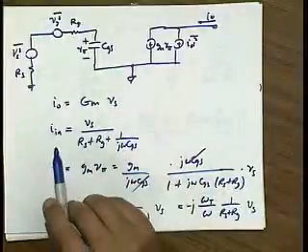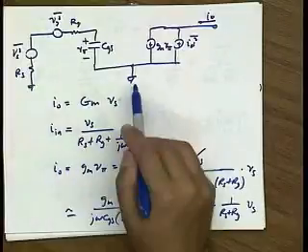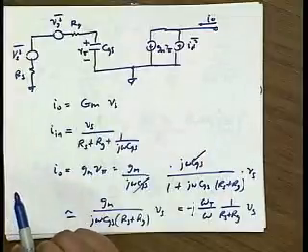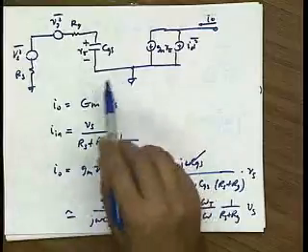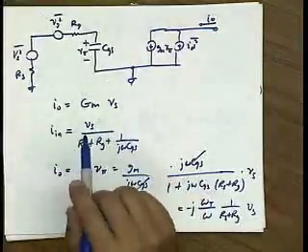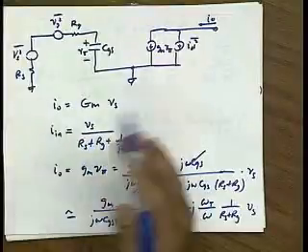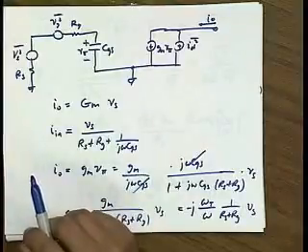Anything else that we've neglected? Source resistance? Oh, you mean the resistance down here? Yeah, that's true. We have neglected that, and that may be important in certain applications. Usually, we like the device to be fairly big for the LNA, so the source resistance won't be too large, but certainly something that we could include in the calculation. Good midterm problem.